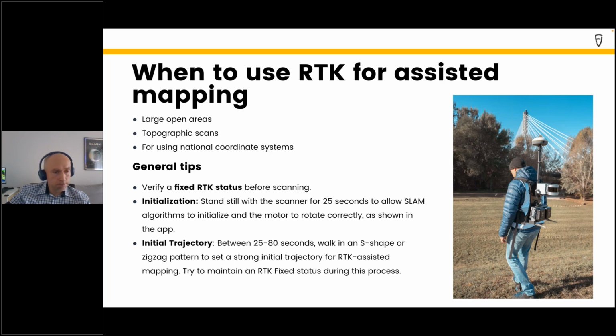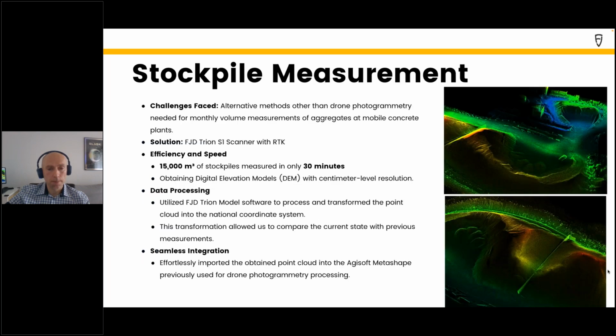And please try to maintain the fixed solution during the whole scan. If you can't achieve the fixed solution, you'd better scan in handheld mode and then connect this scan to the scan made in assisted mapping mode with RTK. And the next showcase example is also made with this solution.